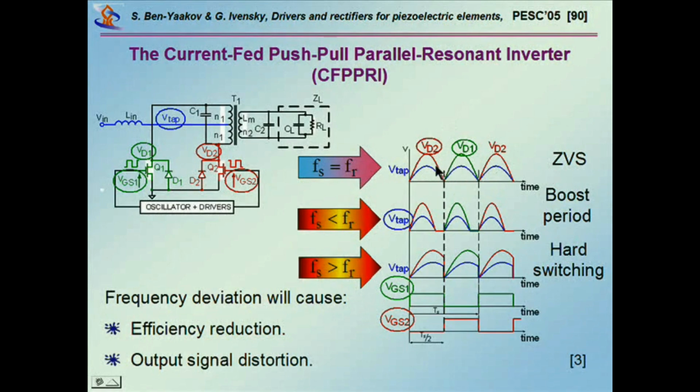Yes, please. It will be a real problem if you neglect the L-in. If you have a voltage set, then you get into the unbalanced condition. That's correct. If you have an inductor, then you'll have a non-symmetrical swing between the two sides, and this will actually compensate. This will do the reset. Actually, the reset will be automatic.